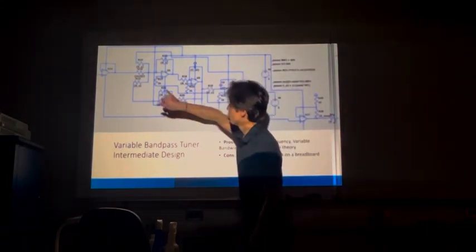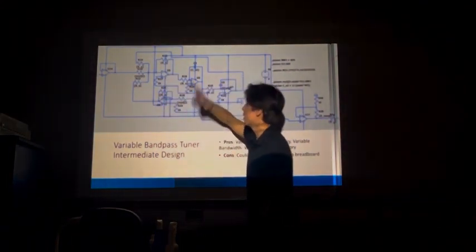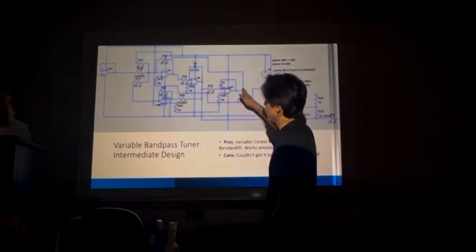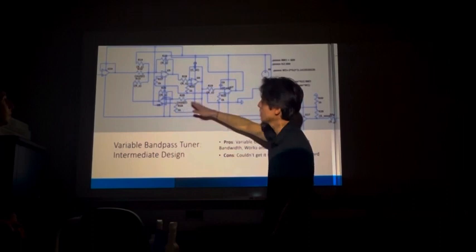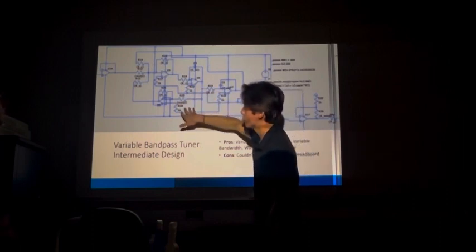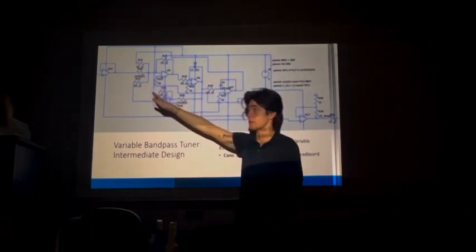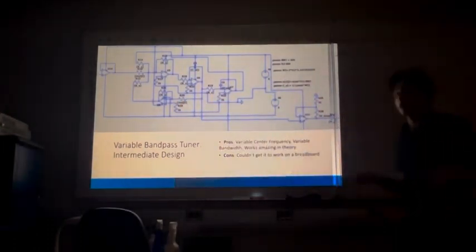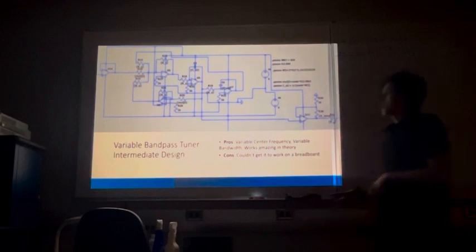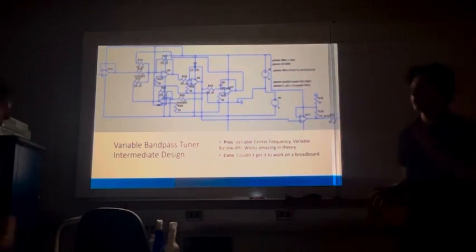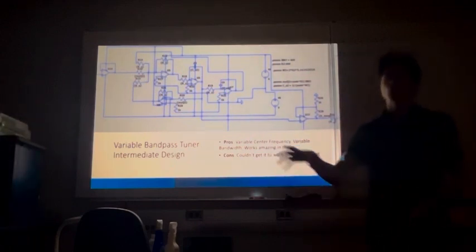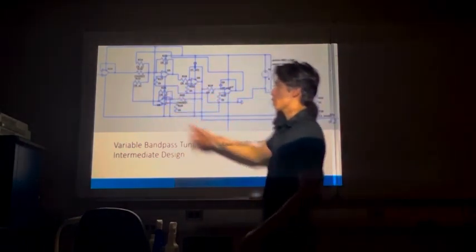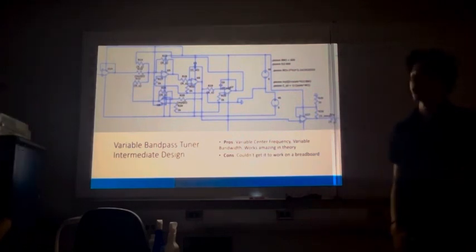So idea being with this topology, you get a high-pass output, a band-pass output, and a low-pass output. And we have different feedbacks, so the low-pass output feeds back into the summing amplifier, in addition to the band-pass output being amplified, then going back into the summing amplifier again. Now, with all these feedbacks occurring, and you're having these three filters in parallel, you can get a lot of cross communication. Different filters will have different currents going into other filters. So we added a buffer at the beginning to make sure that everything's isolated and to reduce reflection coefficients.